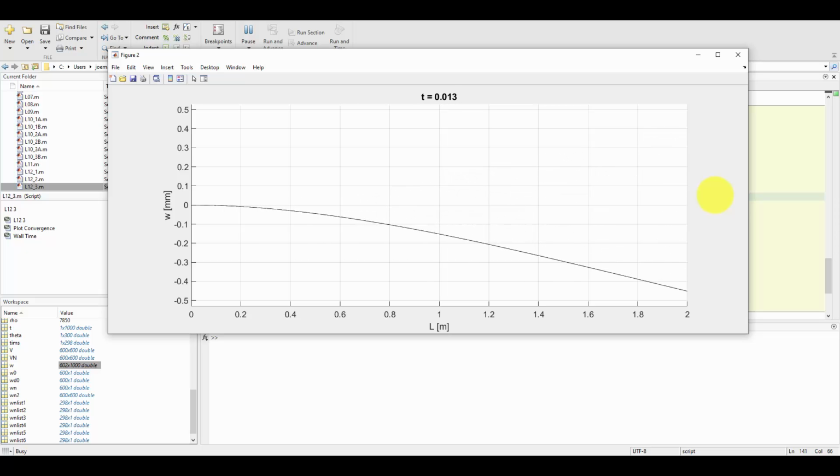However, in problems like this where it's just the beam vibrating, we do need to treat it as a continuous object, because as we see here, we will get a lot of error if we were to say, you know what, it does behave as a 1 degree of freedom system. We would be missing all of these oscillations that are happening, which would not be reflected by treating it like the static beam equation would predict.